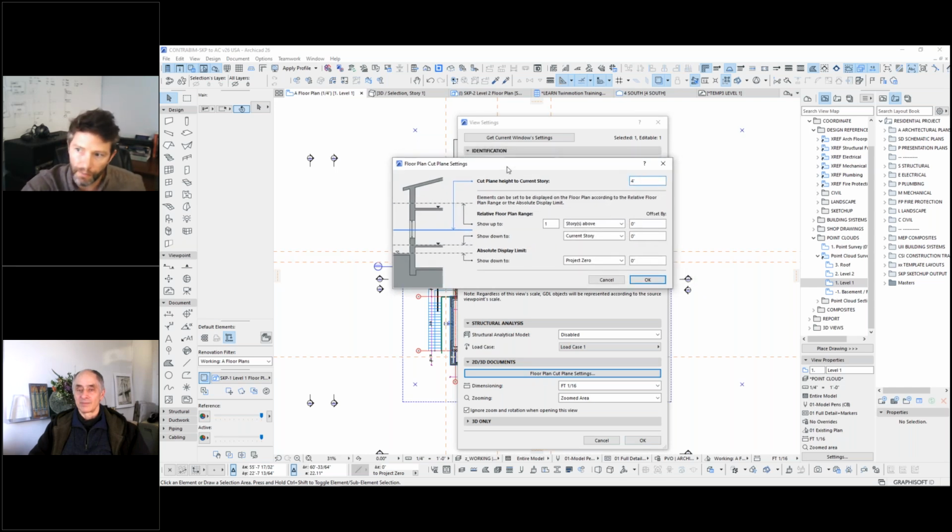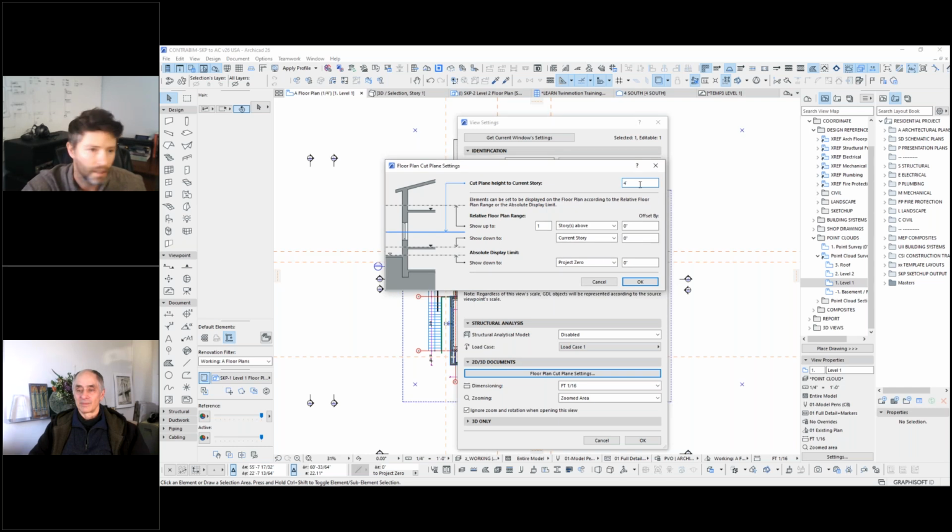And I'll set this, for a floor plan, probably around maybe 1 foot or 2 feet to 4 feet, or 2 feet to 6 feet is a good range. That way you get all the clean walls, you don't get all the junk on the floor, and you just get a nice clean line representation of your walls, maybe casework, openings.